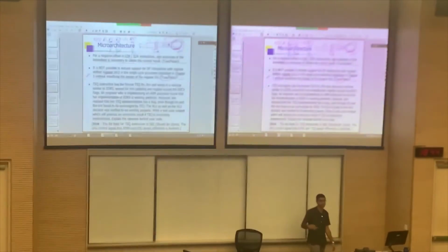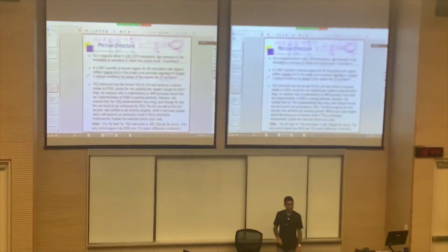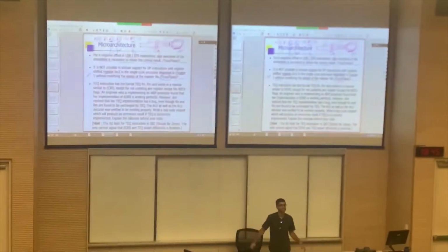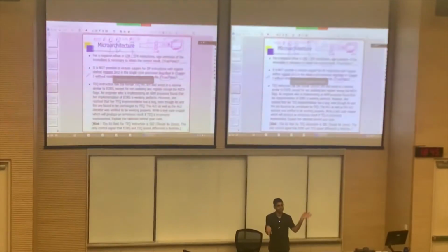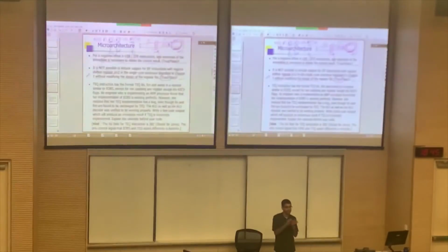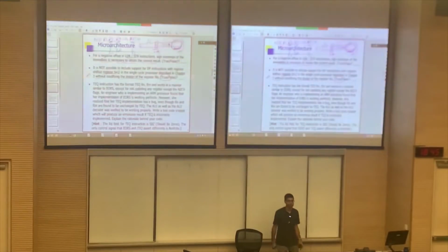Yeah, micro operations. Basically split this instruction into two. And the instructions to which it is split into need not even be instructions in the valid instruction set. Then freeze your PC for one cycle, because now one instruction is executed as two, right? So you have to freeze your PC for one cycle so that another instruction will not come in. And then send these two over two different cycles. That's the idea.